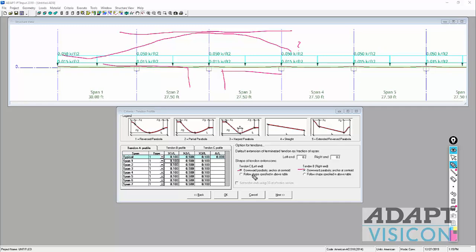Or does it just follow the shape function for this cable, for this reverse parabolic shape? If it follows a shape function for this, then you're likely going to have the centroid here and this eccentricity, and you're going to crank a moment into the slab at that location. So typically we're going to anchor at the CG of the slab. We'll use the defaults in this case.